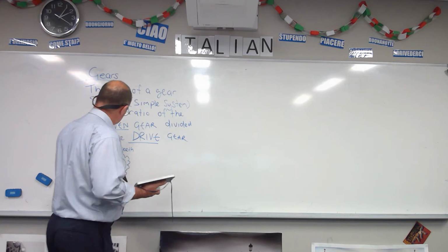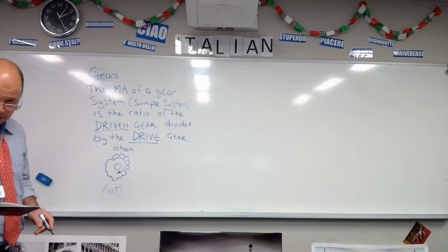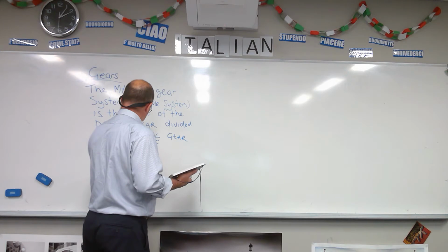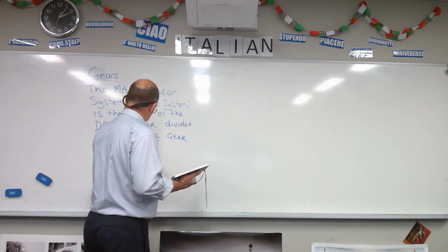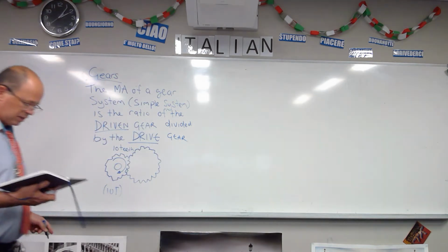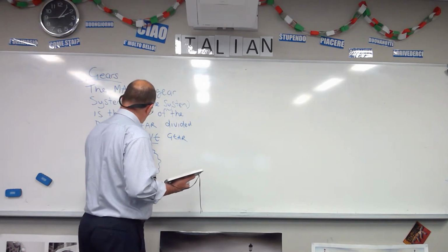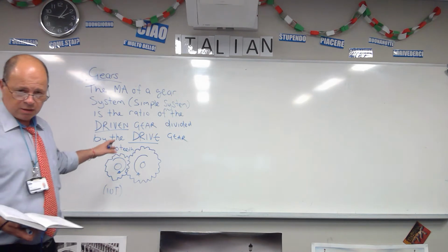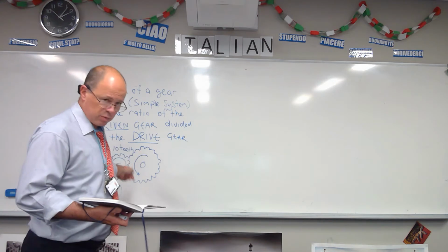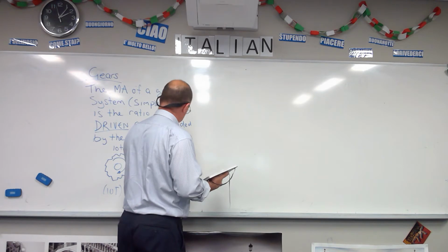Quite often you'll see that written as 10T, indicating the number of teeth, and it is going to be driving another gear that is bigger. These gears mesh with each other, and so this gear is going to spin in the opposite direction. So when you have a pair of gears, the drive gear makes the driven gear spin in the opposite direction. For this one, we're going to say it has 20 teeth.